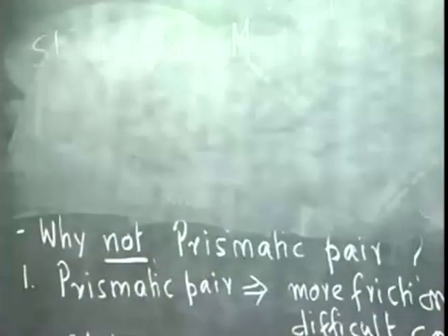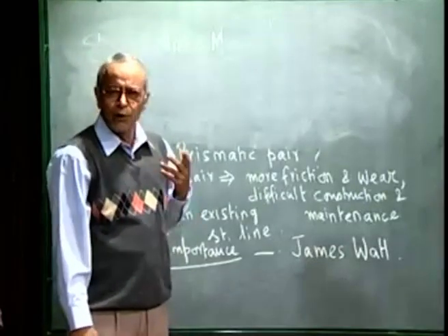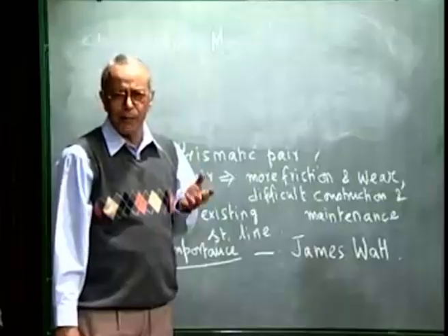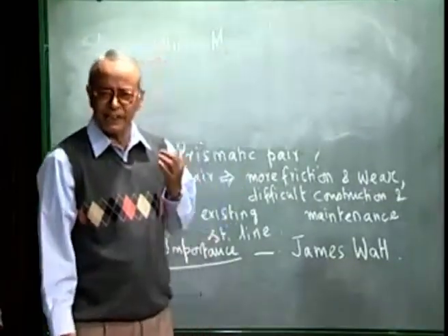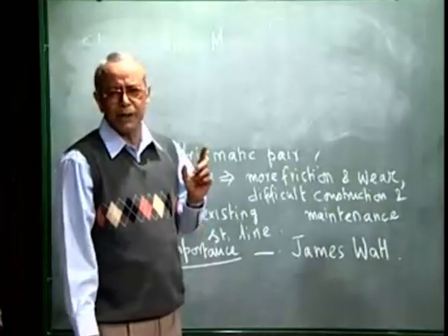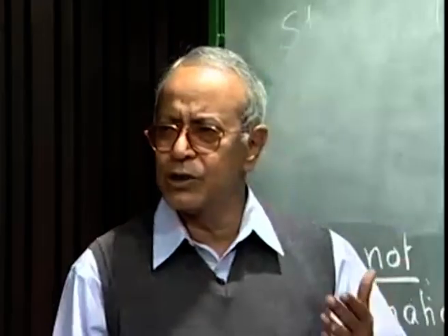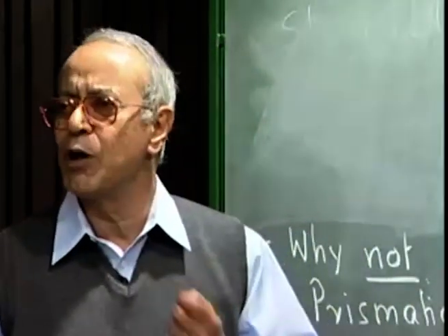Well, now it is known that it is not possible to generate an exact straight line by a 4R linkage. No point of a coupler with any dimensions of the links can produce a perfect straight line. However, it is possible that a portion of the coupler curve can fairly reproduce an approximate straight line if the link lengths are properly chosen.